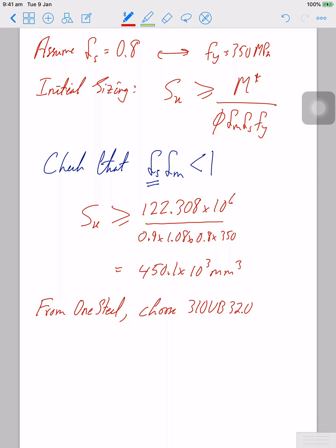So we're going to pick out the data from the catalog, that is the thickness of the web, your d1, which is exclusive of your flange thicknesses, I think, or the depths. Get 282. The total depth of the section is 298 millimeters.